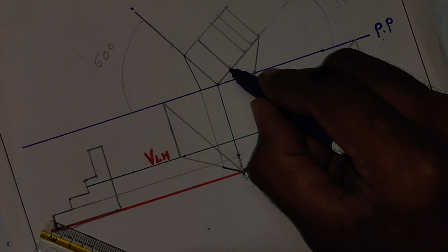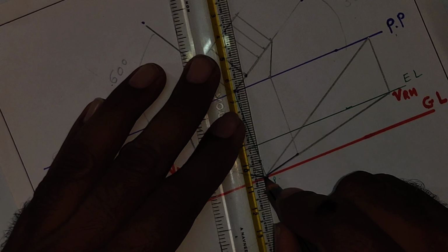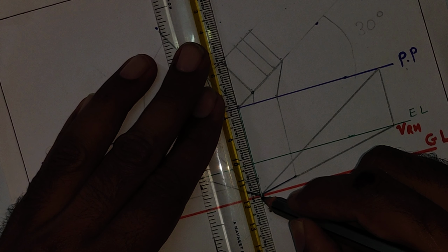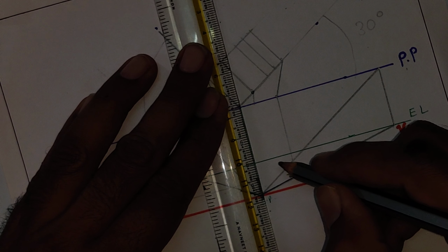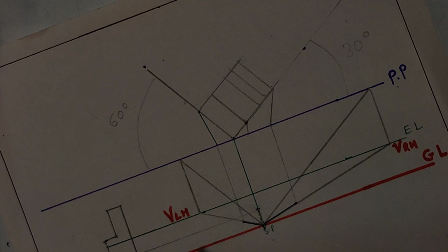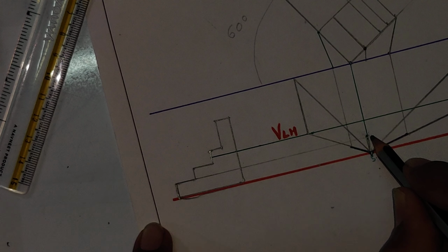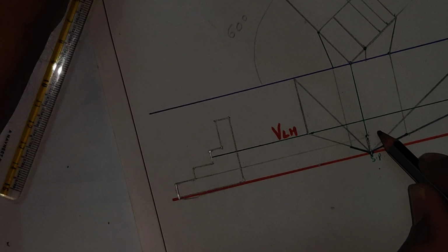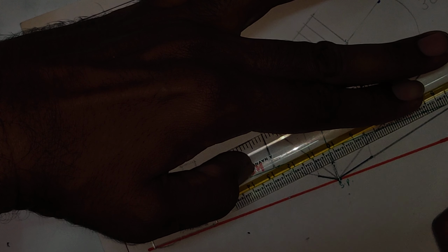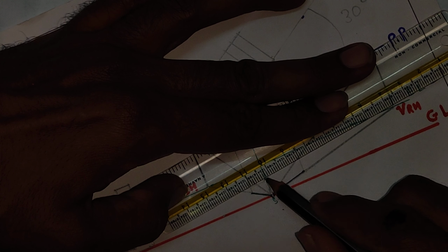This we'll target this point. The procedure is the same. Station point and that point project to the picture plane. After that draw a straight vertical line. So before drawing this line we have to mark this point, because this point is here, right? We'll draw this line. This line is exactly going to the right hand vanishing point. So we'll first join this point to the right hand vanishing point. As you can see, can you see? Yes, the right hand vanishing point.